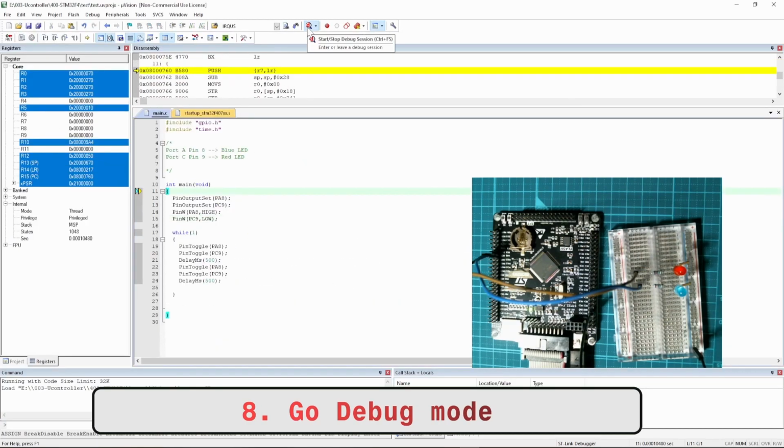the first thing you can see is my microcontroller has stopped moving. And that's fully normal because now your microcontroller has stopped and he's waiting for you at the first instruction here. So now the microcontroller is waiting in the first instruction here. And there are two ways to run it. You can click here, this is run mode. You just put your microcontroller running directly, or you can go on this one, step over, and go step by step through the code.